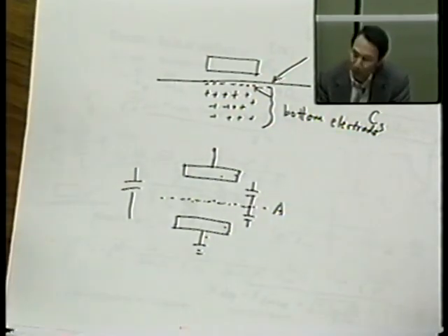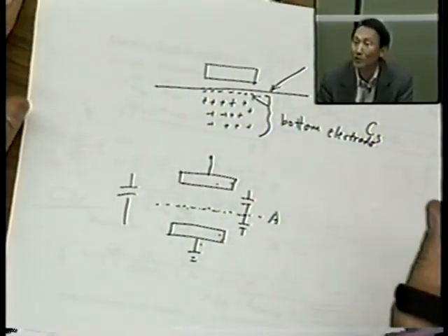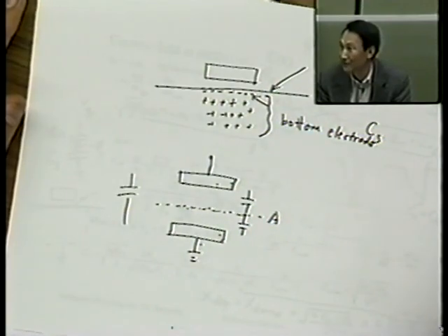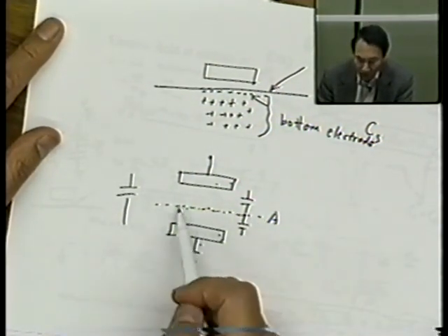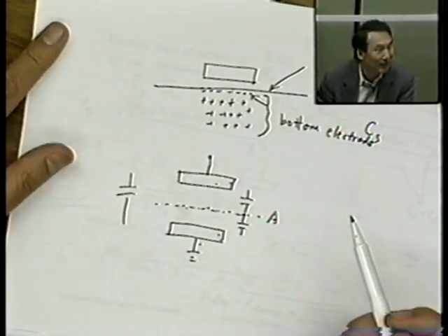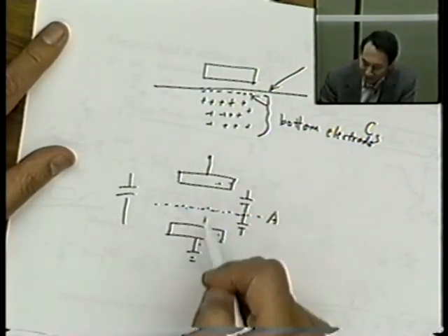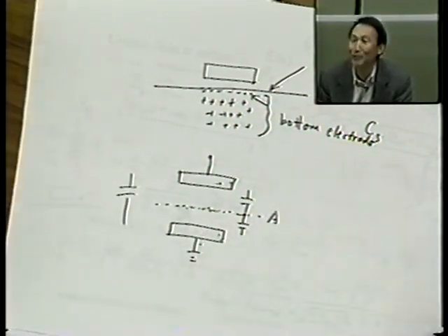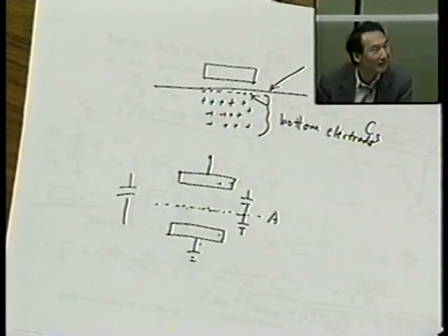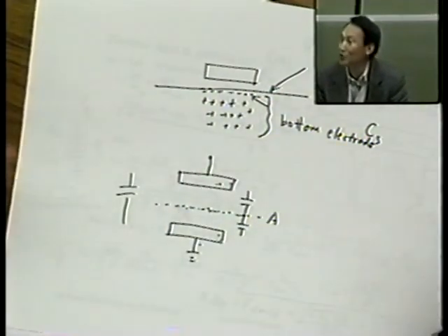So it's in this spirit that I'm asking you to think of the MOS as being made of two capacitors. Just as here, you can argue there's no charge on plane A. That's because the charge on plane A corresponding to the top capacitor cancels out the charge on plane A corresponding to the bottom capacitor. Following what I'm saying? Therefore, in this surface electrode, there's no charge.